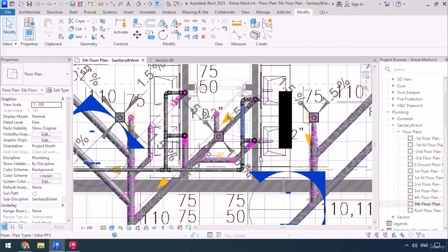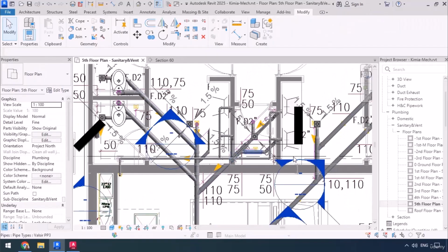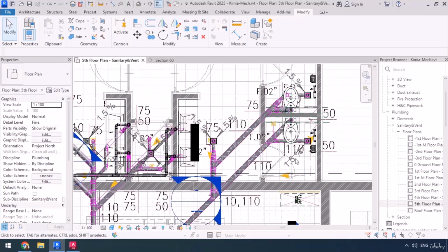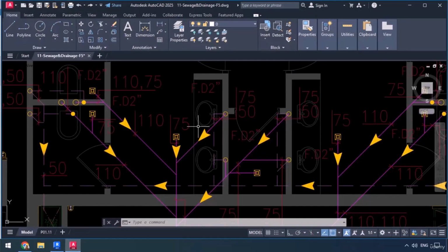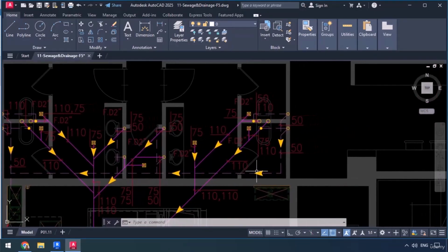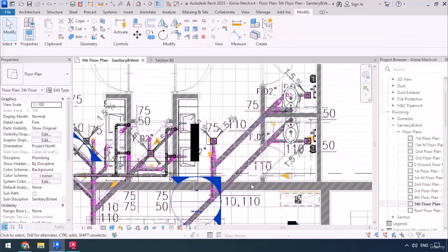Alright, so we've drawn this vent pipe, and we've also figured out up to which elevation our vent pipes need to be. Now the other vent pipes that we're going to need to connect are for these toilet fixtures over here. So we're going to go take a look in the plan, and here we are. We've connected these vent pipes, and now we're going to have to draw this pipe all the way to here and connect it to these two vent pipes through the wall, which are for these toilet fixtures.